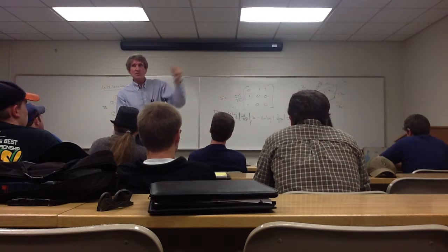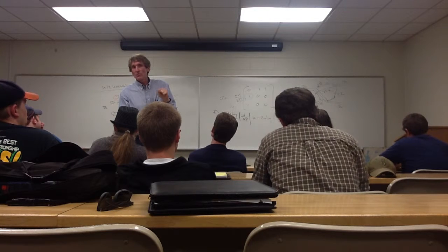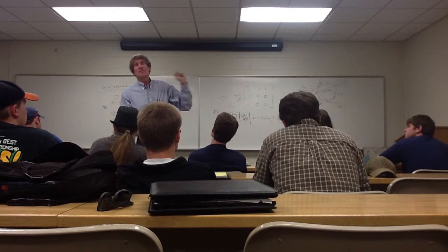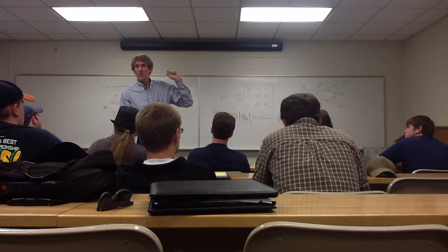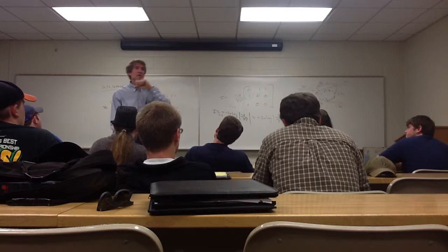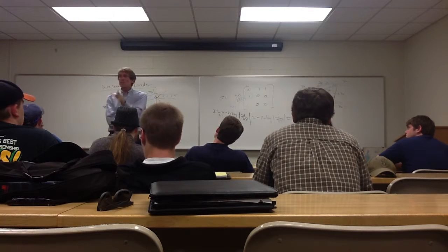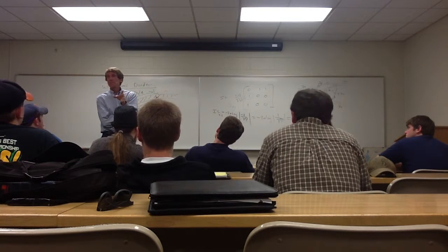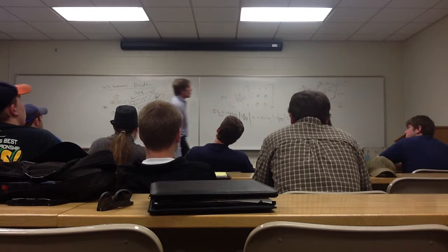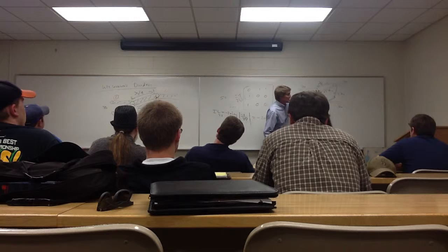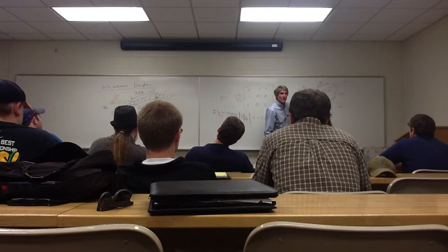Suppose I try to use this, suppose it was for 75 ohm cable, for charter cable, and I used it with 75 ohm cable, but it was being used in a different frequency band. What would happen? Anybody? That's right. This would no longer be a quarter wavelength. That's a physical length. That quarter wavelength is only true for one frequency.